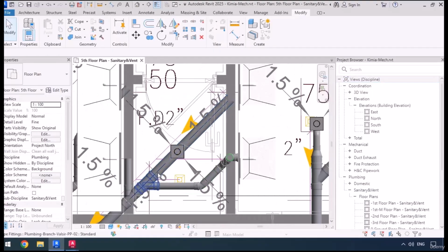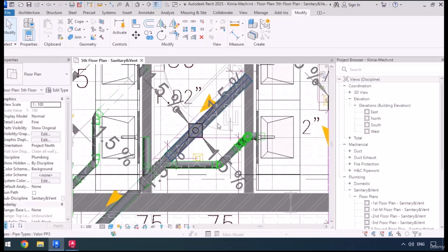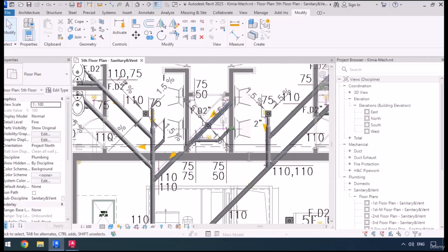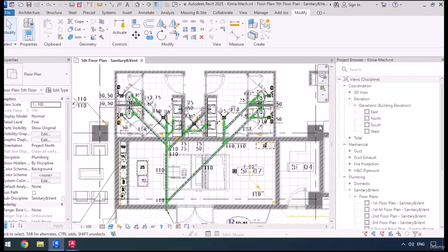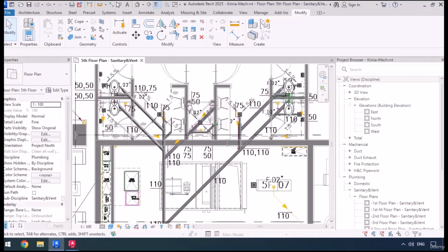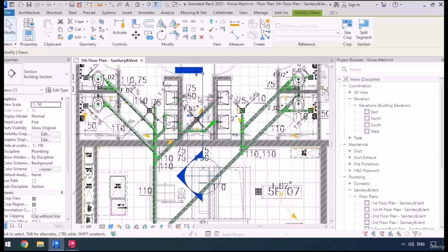So you see, first we're going to have to draw an out pipe from this floor drain, and then lead it towards the pipe below it, and we also need to make sure that we use a trap. But we also notice that there are 2 columns around the plan, as well as a beam. So for example, if I create a section in this direction, we could understand that better when we see it. So I'm going to also make the section tighter, then right click and go to view.